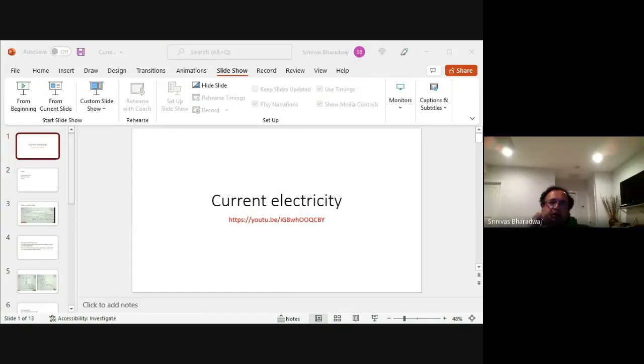Okay, so now the EMF is a contour integral of E dot dl. Now J is equal to sigma E. You know all this. V equals IR, right? J dot A is the current, right? So that is what happens if you look at the vectors inside a battery.